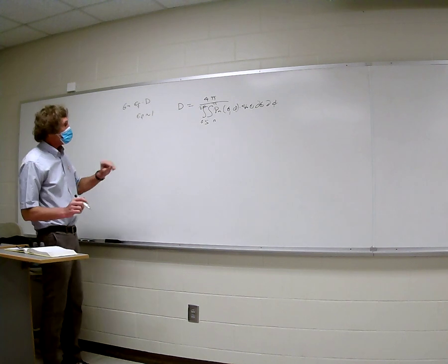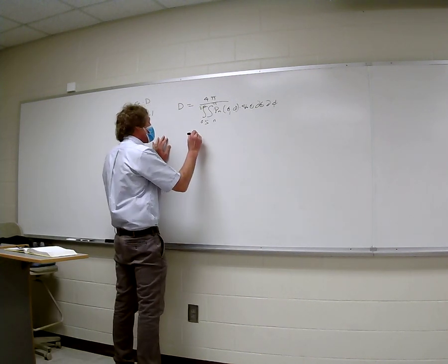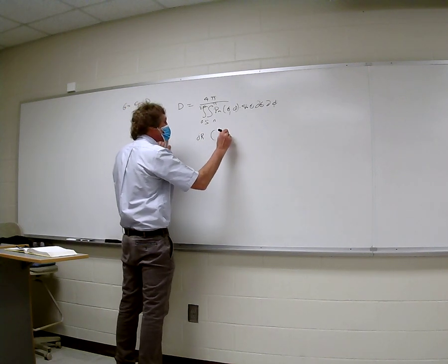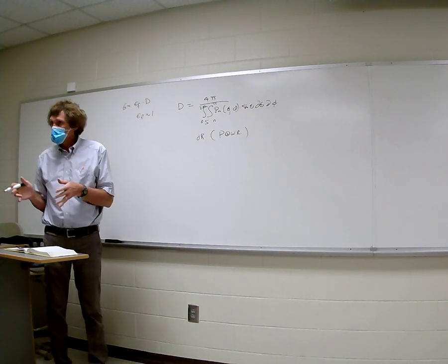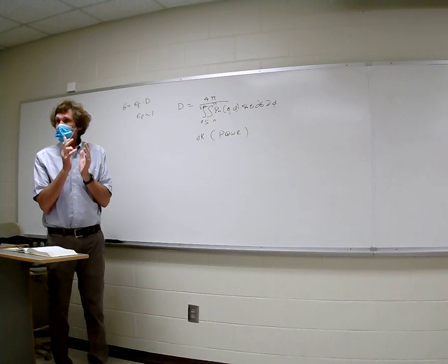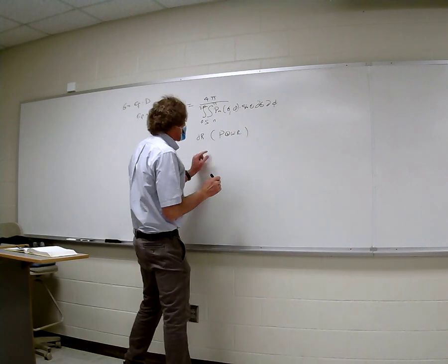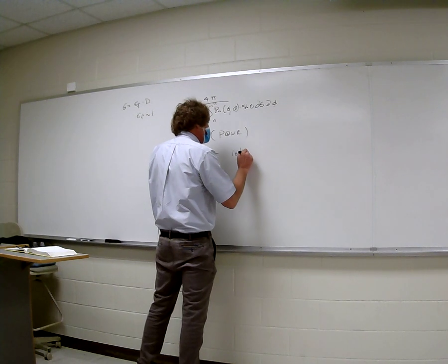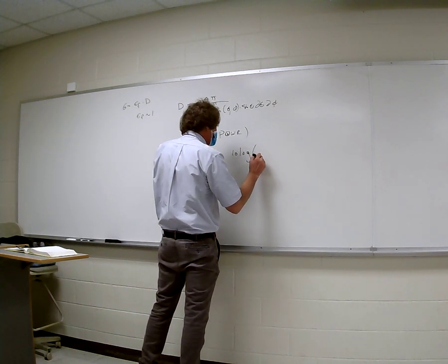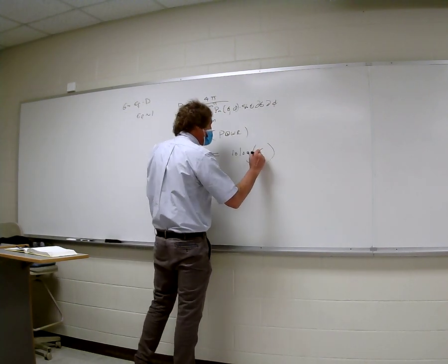All right. Now, when we talk about dB, this is the real thing. Any number in dB, and put down if it is a power-related term. Gain is related to power. It has to do with the gain times the isotropic power density is the power density that's increased by that focusing power of gain. Okay? So if that's the case, we talk about dB, it's equal to 10 times the log of whatever the number is, linear. Now, if it's gain dB, this would be gain linear.